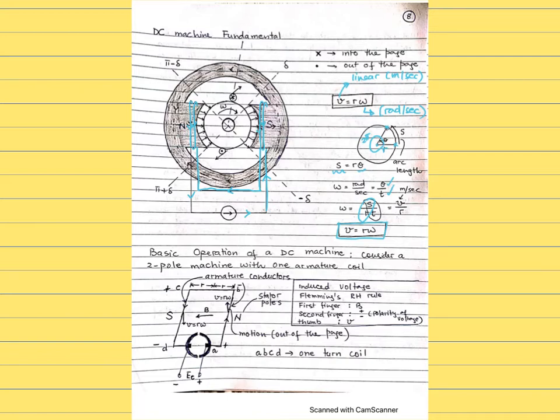One more thing which we're going to pay attention to in here: the pole area, the coverage of the circle under the pole, is given by these lines. So under the pole, same as on the other side, is limited to minus delta to delta. So this is the angle 2 delta. Okay, so outside of this range, and the same on the other side, so this is also 2 delta, there's no field in here. That is what we are assuming in this case. Field is 0. So B is 0, let's say. Same as for this side. B is 0 outside of that 2 delta limit.